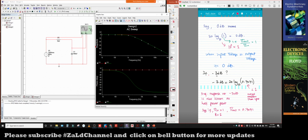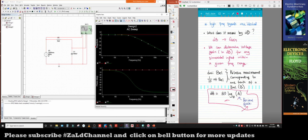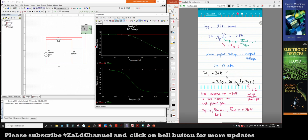How about -3 decibel? Okay, so this is an example calculation of -3 decibel, using the same equation here. Using this equation, we can calculate for -3 decibel that the ratio of voltage output to the voltage input is 0.7071, which in this case is less than 1. What does it mean by less than 1? It means that the voltage output is smaller than the voltage input.